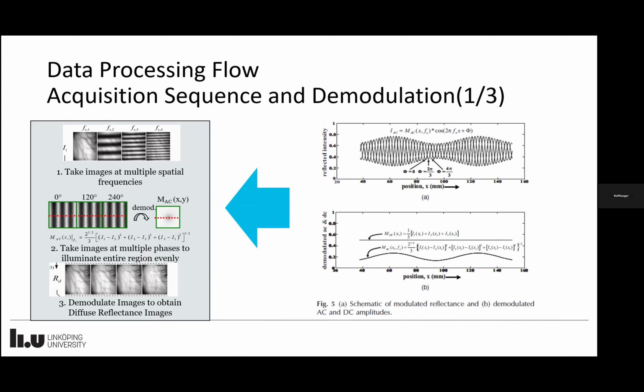And so you would lose spatial information, because you have to look at your neighboring pixels to really determine where in the sinusoid you are, and then what that amplitude must be. When you do 3 separate phases, again, you have this overlap, and mathematically, it becomes arbitrary. So long as they're evenly spaced between each other, you can calculate what the envelope function is.